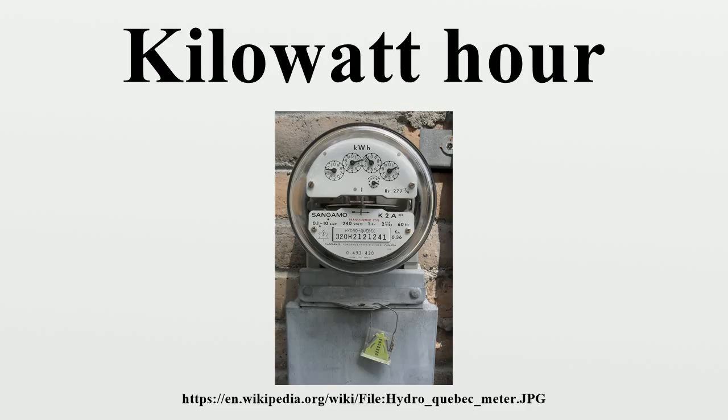A kilowatt-hour is the amount of energy equivalent to a steady power of 1 kilowatt running for 1 hour, or 3.6 megajoules. Energy cost can be illustrated in a similar example. A 100-watt light bulb turned on for 8 hours uses 800 Wh or 0.8 kilowatt-hours. If the energy cost is 25 cents per kilowatt-hour, it would cost 0.1 kilowatts times 8 h times 25 cents per kWh, which equals 20 cents. Whereas individual homes only pay for the kilowatt-hours consumed, commercial buildings and institutions also pay for